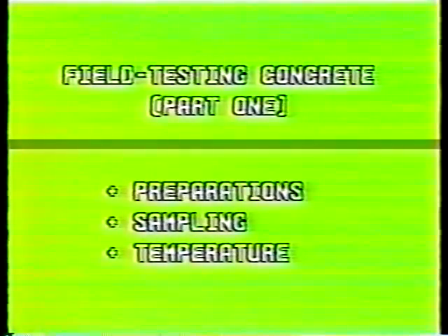Now on to sampling. Getting a sample of concrete to run the tests on. Actually, the word sample isn't quite enough. What you're going for is a representative sample. You want to make sure the concrete that you're testing is typical of the entire truckload.